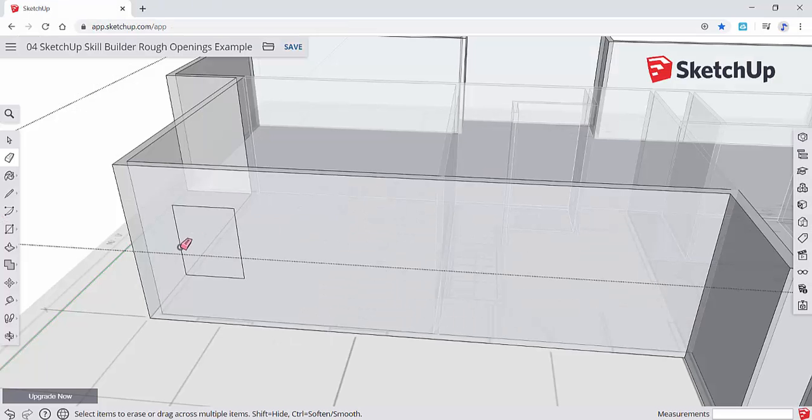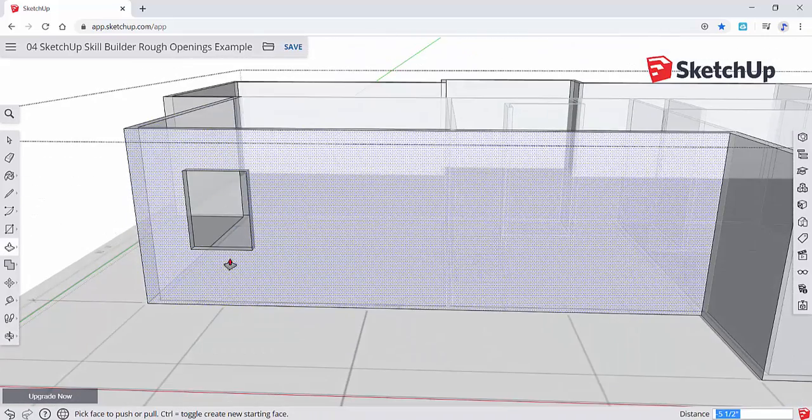Okay, and then he goes to the push pull tool, keyboard shortcut P for push, pull. It's right there. Click on it. Click on this surface. Now if you drag it to the right of your screen, you can actually snap it to kind of like the back. If you go to the left, it comes out. See how it's coming out to the left, but to the right, you want to snap it on that face, and it will cut a hole into it.